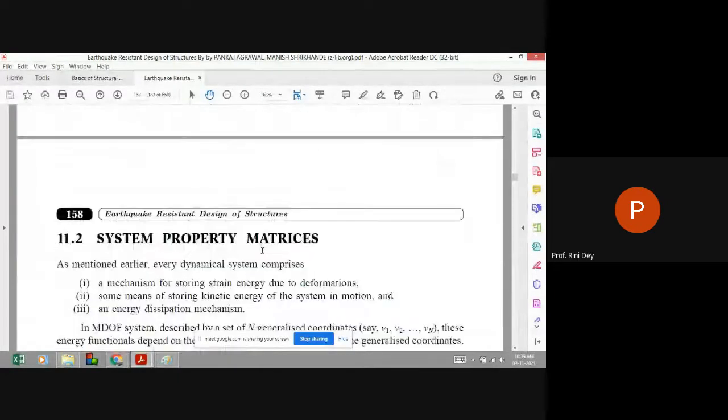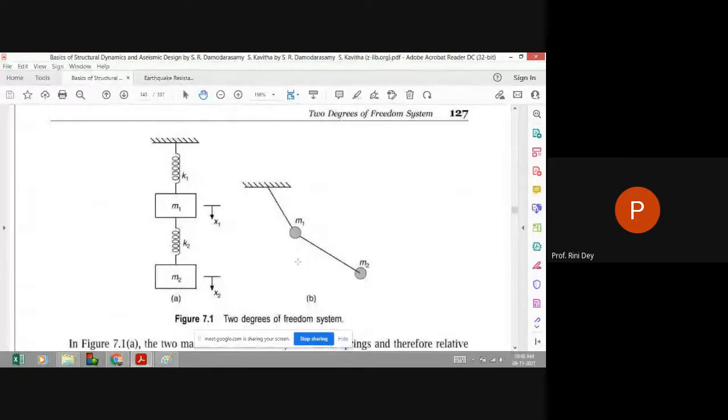So now here let us come back to this. These were the same things. Sorry. So we were looking at the pendulum scenario. Now see that the pendulum can also be represented as a 2 degree of freedom system, such as a mass spring dashpot system. Here the dashpot is not present, so it is a mass spring system. See here that the mass can be represented as a lumped mass, and that connecting rod can be represented as a spring column, which will have a certain amount of stiffness.